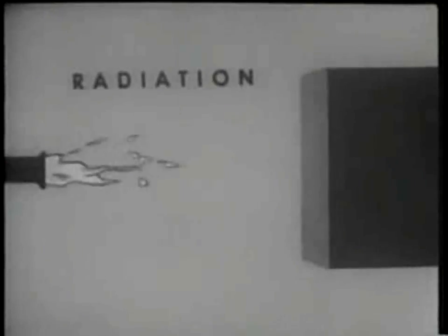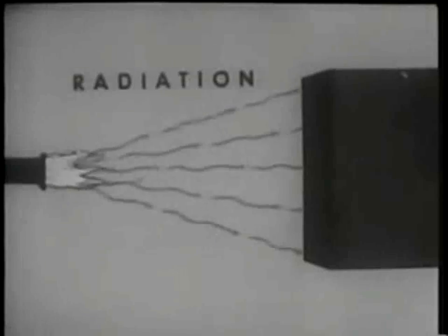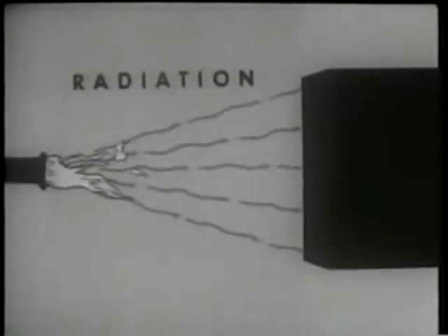The process of radiation involves the direct transfer of heat in the form of waves, without need for a medium for the heat to move through. Refrigeration makes use of all three methods of heat transfer in removing heat from food items to a liquid cooling agent. Heat travels between the food and the cooling unit wall, both by means of radiation through direct waves and by means of convection through air circulation. The heat passes through the cooling unit wall to the liquid by conduction.